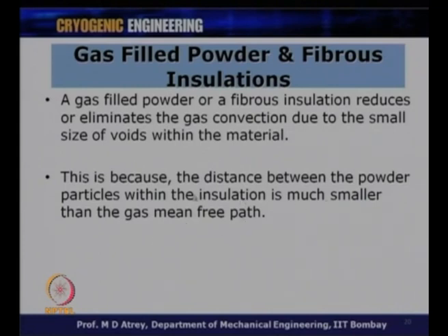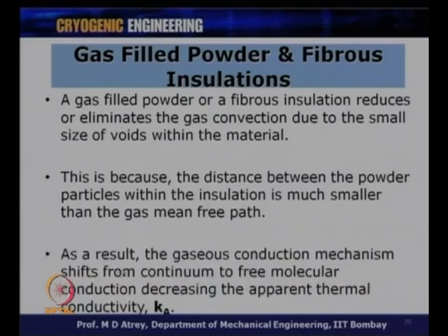That means we are talking about a molecular region for the gas element. As a result, the gaseous conduction mechanism shifts from continuum to free molecular conduction. That means the distance between the particles is so small that the mean free path of the gas is larger than that, and therefore we are shifting from the continuum region to free molecular conduction of the gas, decreasing the apparent thermal conductivity Ka over here.